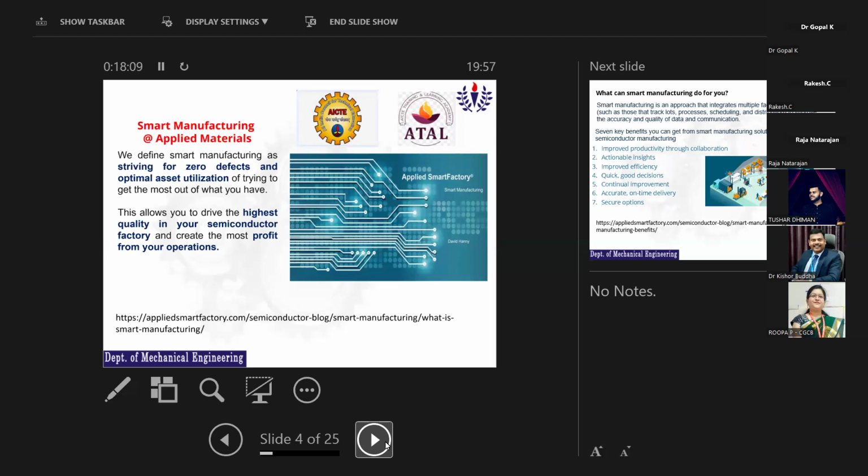So the factory interface, what I referred to, inside the factory interface there would be robots, two robots, sometimes four robots, which would try to push the wafer from one chamber to another chamber with respect to the process needs. So mainframe again, it's a chassis for the chamber or the system. It acts as a stand base for the system, which holds the whole process related modules. And chamber is where your process has been done, and the gas panel.